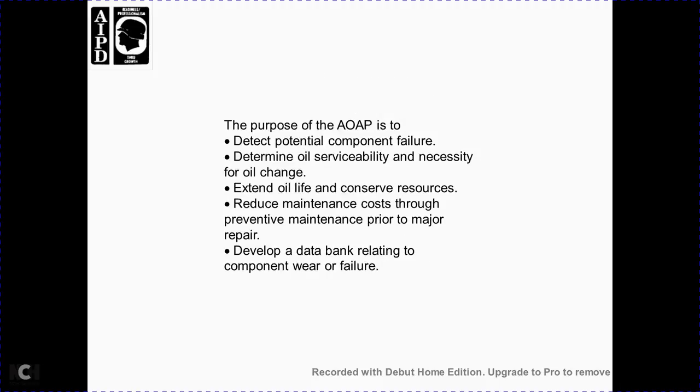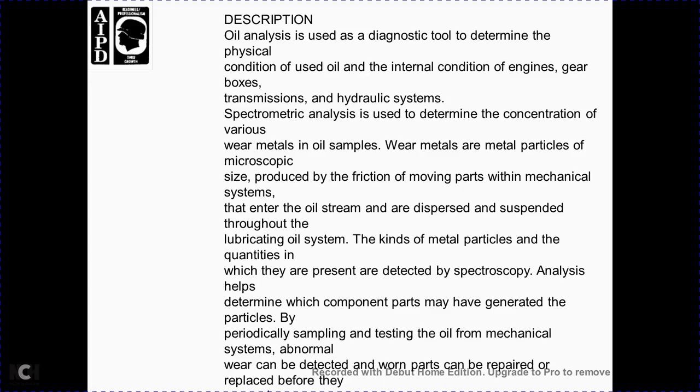The purpose of the Army Oil Analysis Program is to detect potential component failure, determine oil serviceability as necessary for oil changes, extend oil life to conserve resources, reduce maintenance cost through preventive maintenance prior to major repair, and develop a data bank relating to component failure.